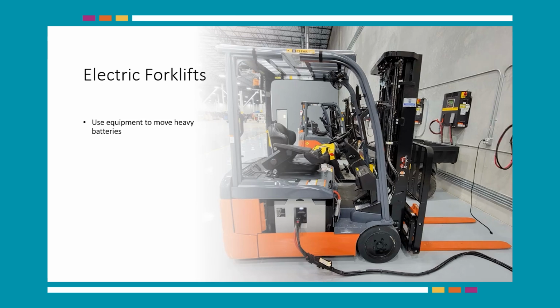Hydrogen gas is generated when batteries are being charged, and if the battery charging area is not well ventilated, the accumulation of hydrogen gas can present an explosion hazard. In addition to providing ventilation, keep battery charging areas clean and free of open flames or anything that could create a spark.